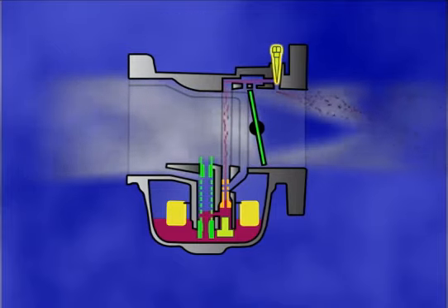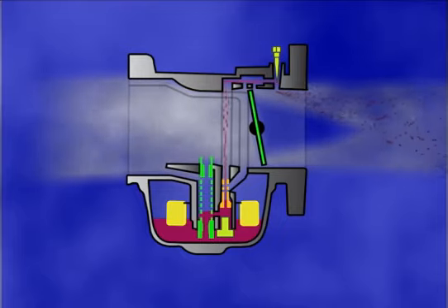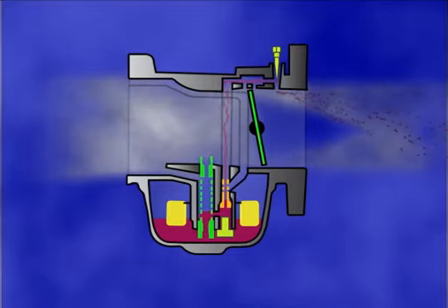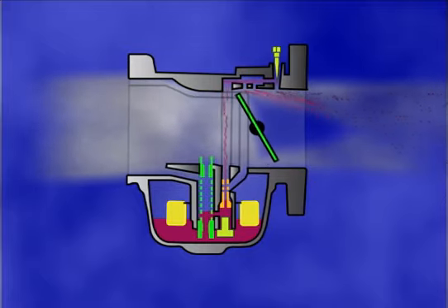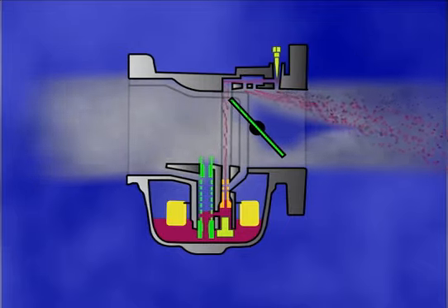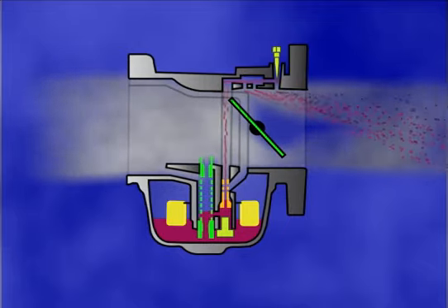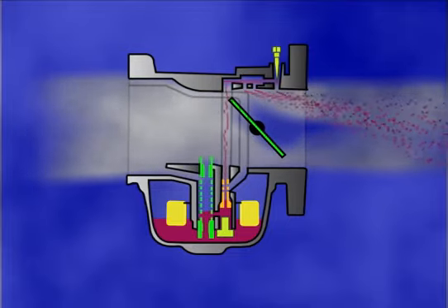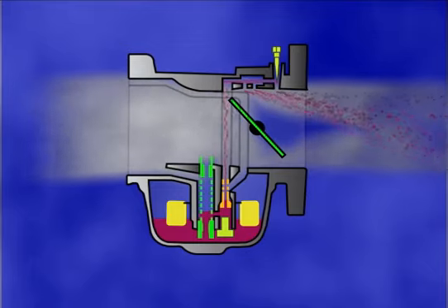A tapered needle, the pilot mixture screw, controls the air-fuel mixture flow through the pilot discharge port. As the pilot screw is turned in or out, less or more air-fuel mixture is allowed to pass into the airstream in the carburetor throat. This provides for adjustment of the air-fuel ratio at idle. As the throttle is opened, the bypass discharge ports are exposed to venturi vacuum, and more of the air-fuel mixture is discharged into the airstream. Pilot jet size determines the air-fuel ratio in the bypass stage.